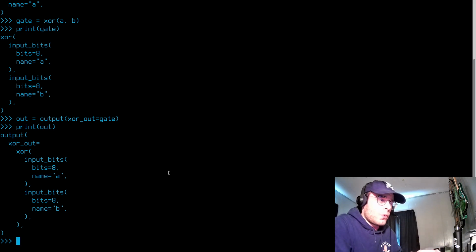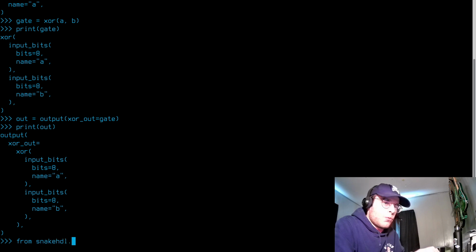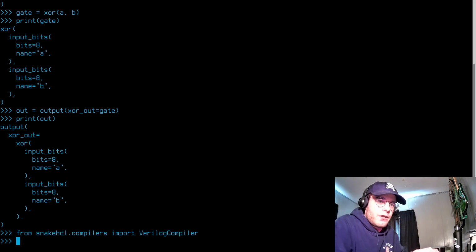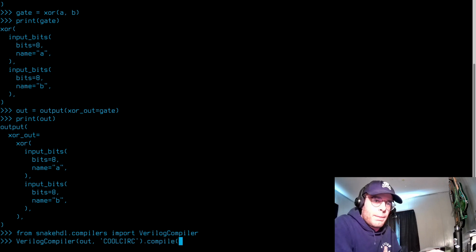Now, what do we want next? We want hardware. In order to do that, we need to import the compilers. We'll do Verilog. We'll import the Verilog compiler, and then you just create an instance of the compiler. You pass in your circuit. You give it a name optionally. The name defaults to circuit. And then on the compiler, you call compile, and that returns a compiled result. And on that result, you can call save to a file path. We'll just call it cool.v. Boom, done.